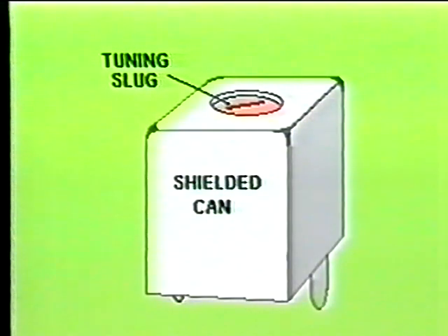To prevent unwanted inductive coupling between the various stages of the superheterodyne receiver, the tuned tank circuits are usually encased in metal shielded cans. Inside the can, the stray RF currents are induced onto the inner walls of the can and sent to ground. The high-frequency currents will travel on the walls of the can due to a phenomenon referred to as skin effect. These shielded cans are used in both the RF and IF stages of the receiver. A properly shielded can will prevent degeneration, regeneration, oscillation, distortion, parasitics, and overall instability.